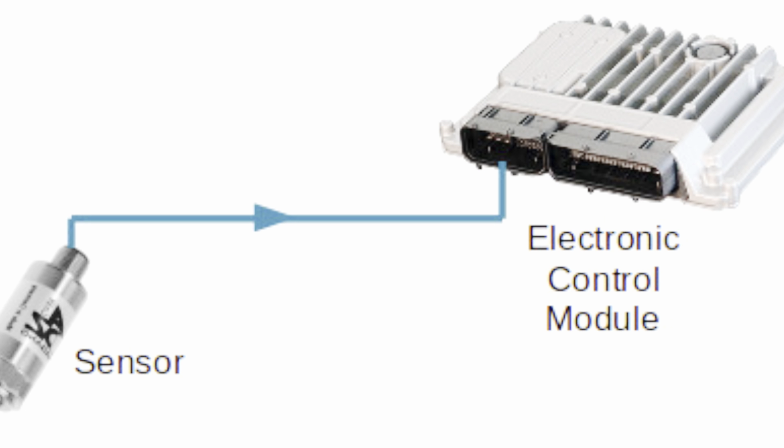Computer controls. The computer uses sensors on the engine and transmission to detect such things as throttle position, vehicle speed, engine load, stop light switch position, etc. to control exact shift points, as well as how soft or firm the shift should be. Some computerized transmissions even learn your driving style and constantly adapt to it, so that every shift is timed precisely when you would need it.